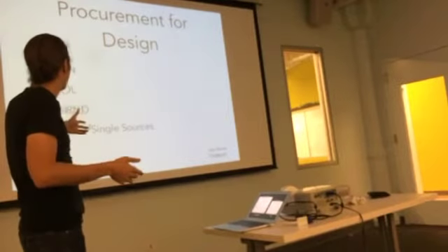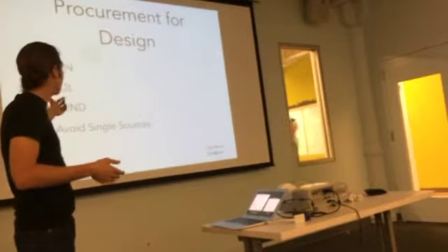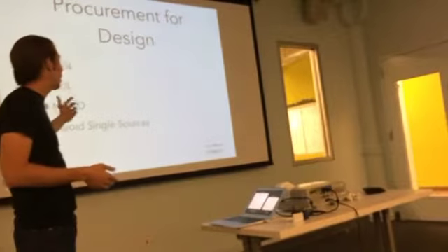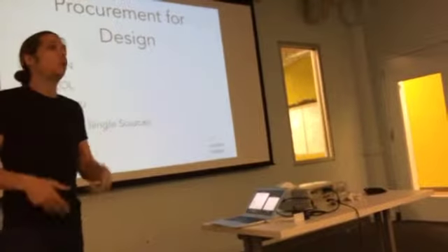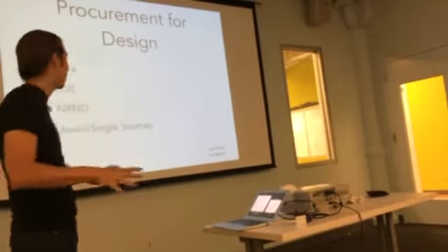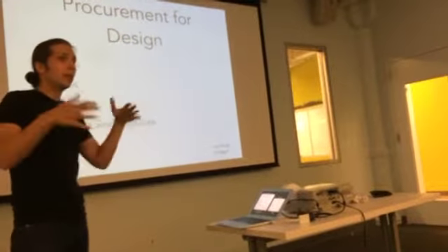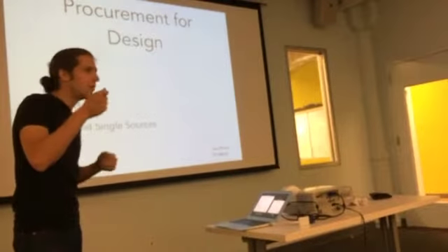And that's what these acronyms are. Product change notice, PCN, end of life notice, EOL, NRND, not recommended for new designs. These are all documents that manufacturers will issue when they're warning you, don't use this part, use a different part. Keep that in mind. Avoid single sources, don't get locked up into a part that is only available from one source.